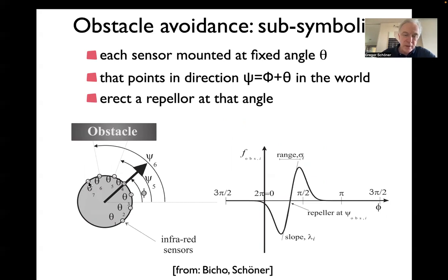There were 7 distance sensors mounted on the vehicle. The big arrow is the forward direction of the vehicle, so the 2 motors would be on the side. And so these sensors sensed distance in some way. The different implementations would use different sensors. One example would be an infrared light that is sent out, and you measure the amount of light reflected back, and that would decrease when it's reflected back from a surface that's further away. It has a certain directional sensitivity.